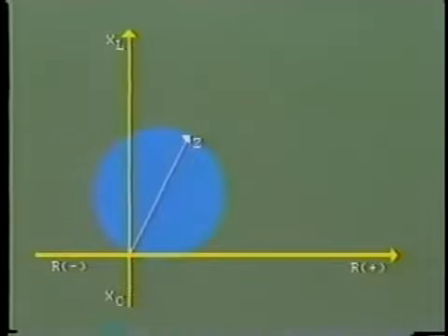The main feature of this relay is that maximum closing force of the relay occurs when the impedance is at a specific phase angle, usually about 60 degrees. This is similar to the phase angle of the line conductor impedance. The result of this characteristic is that as the impedance phase angle changes, let us say becomes smaller, then the unit will operate only for a lower impedance, that is, a higher level of current.